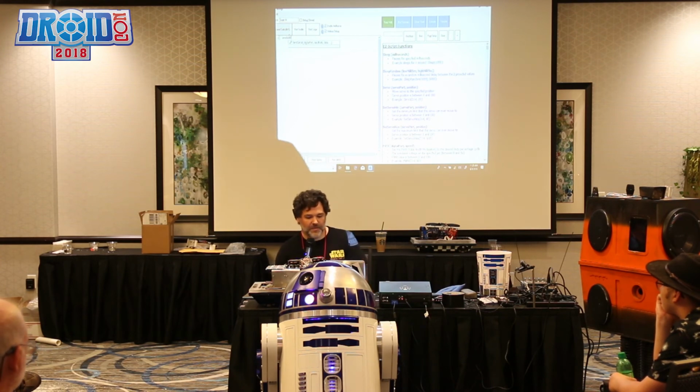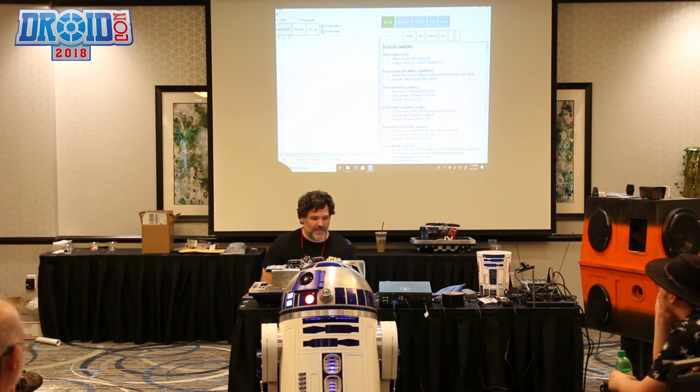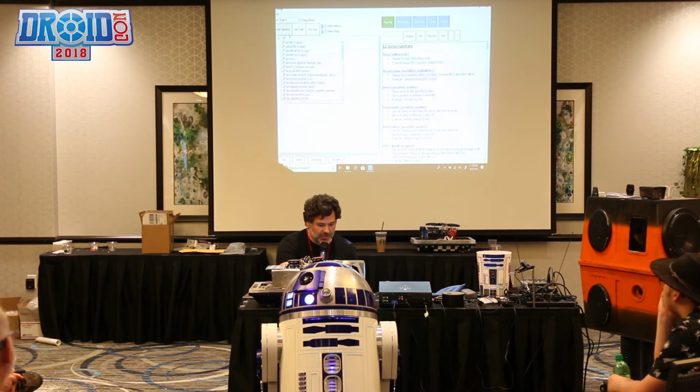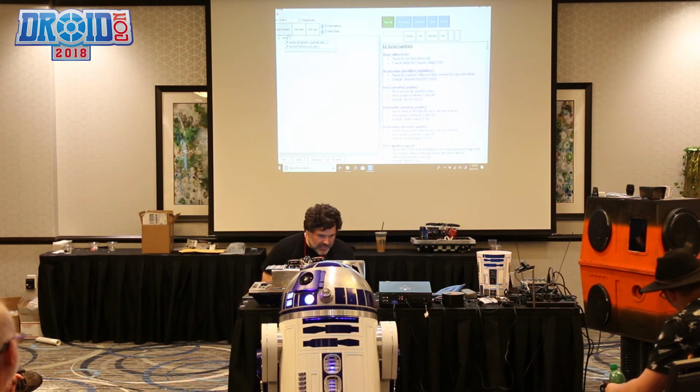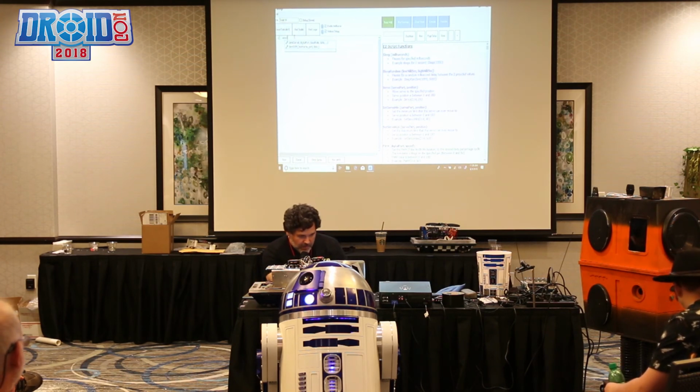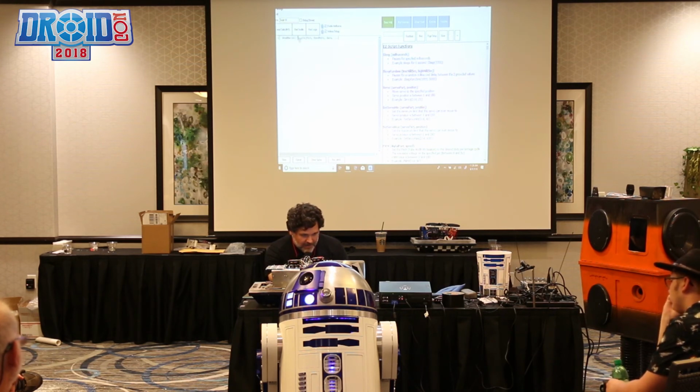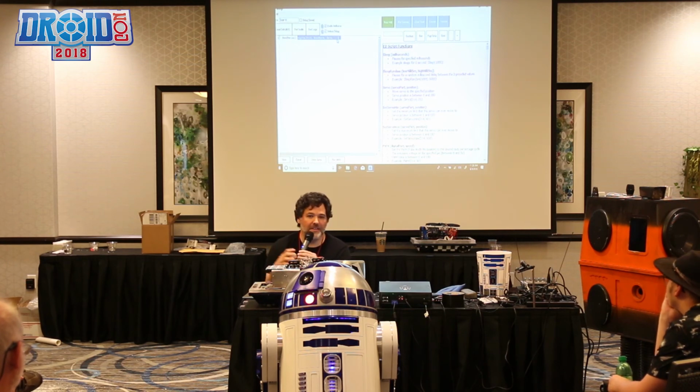Sorry, let me back up. It starts to populate as you're typing. So there's a send serial and a send UDP. We can go send serial, and now all we have to do is fill in the digital port, the baud rate, and the data we want to send. Then it will control anything over send serial, or I2C. You can do whatever you want with this.